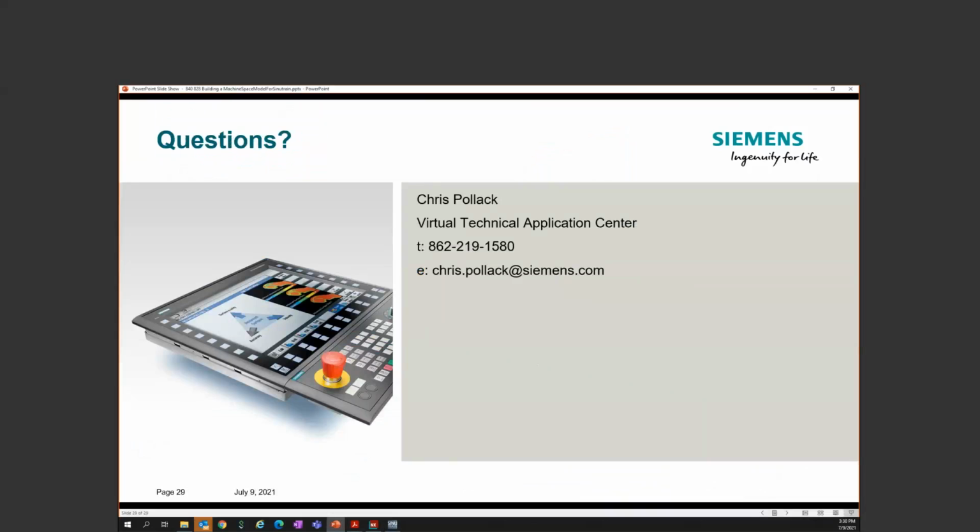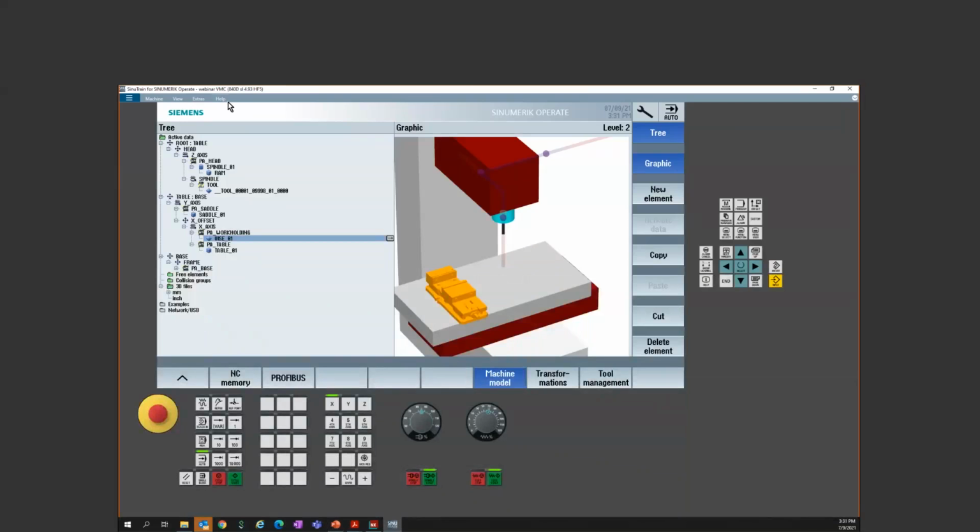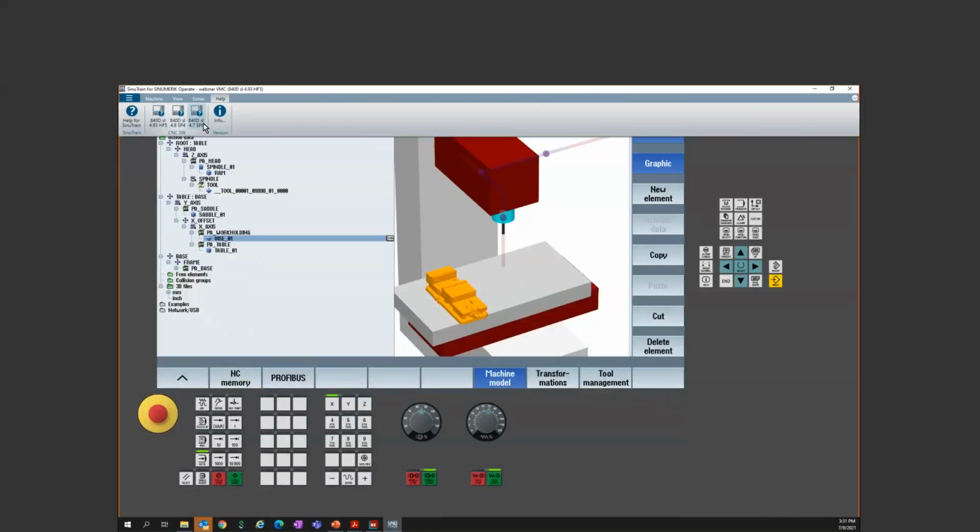So we got the STL, hopefully, Daryl, that started to make sense with bringing in STL files. We got Steve's question: what version of SinuTrain supports this machine space model technology? We initially came out with it in 4.5, but it really wasn't fully released until 4.7. So you would want to have version 4.7 or newer. What I just did all this in is our latest version of SinuTrain, which is 4.93. I have three different versions of SinuTrain running, and we did it in 4.93.